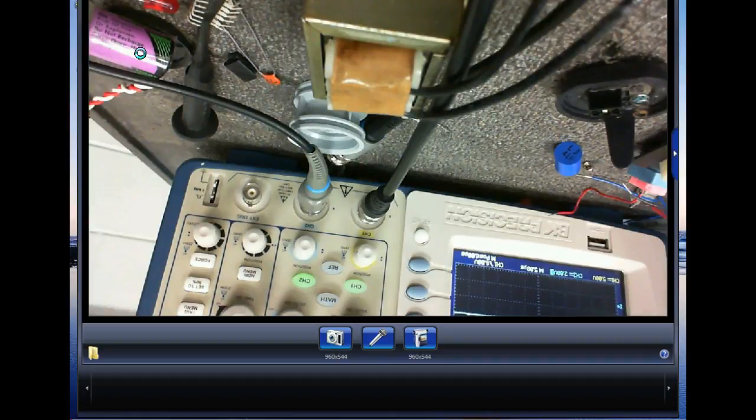So, like I said, you don't even have to have a transformer. If I look at the input, what we used to have on the old power supply is this one right here, so you've got a transformer. This has a switch, so I have to switch it between 115 and 240. That would be 115 over here, and in the middle you switch it over to 240. And that's because it's got a transformer.